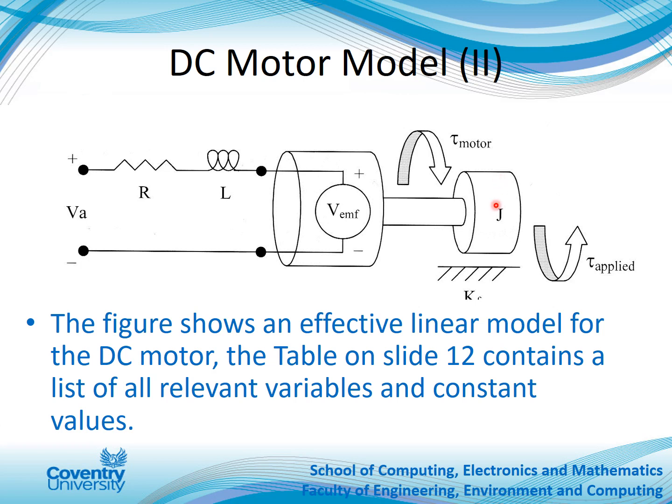Here you've got your rotor inertia, J, measured in kilograms meter squared. You've got Kf, which is the frictional constant, down here, and you've got the torque constant Km measured in Newton meters per amp. The back EMF constant Ke is measured in volts per radian per second. Ks is a speed constant, in radians per second per volt, and then there's the regulation constant.